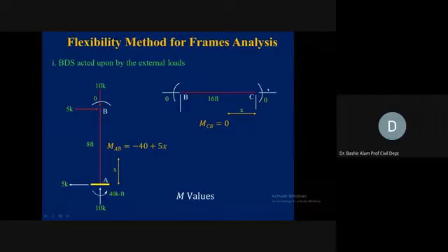So at C, as there is no load, all the member end actions at C are 0 and all member end actions at B are also equal to 0. Member AB, now this 5 kip cannot be put on this BC member because we have removed the resisting capability here. It can be only resisted at joint A now.